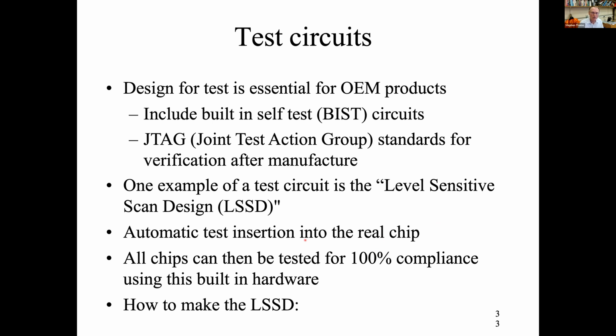The standard one is the level sensitive scan design, LSSD, and this enables chips to be tested. Essentially, you're looking at all the key logic parts of the chip and making sure that they're working. So how does that work?